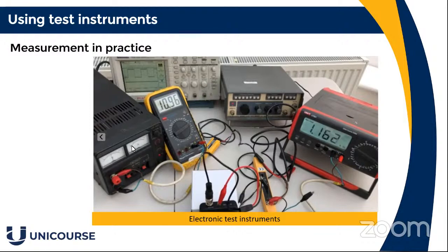That is so convenient. As long as it's calibrated, you put a circuit board under test across the supply, and all of a sudden the ammeter shoots right across, and you know that it should not be drawing that current, so you immediately switch off. So that has both measures. That will also allow us to look at the voltage that we set, and we can also look at the current drawn from the supply into the board.